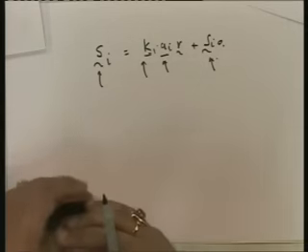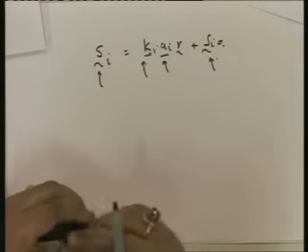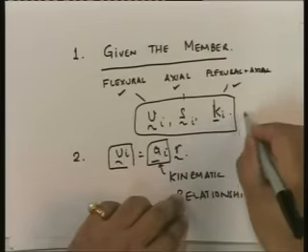Okay? So, in essence, the point that I am trying to make here is that in the stiffness method, whether you have a truss member, a frame member where you neglect axial deformation, or a frame member where you do not neglect axial deformation, all that does is it only affects this. Nothing else.